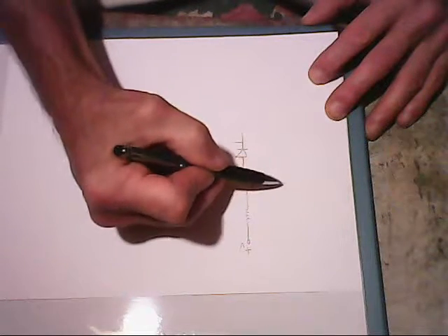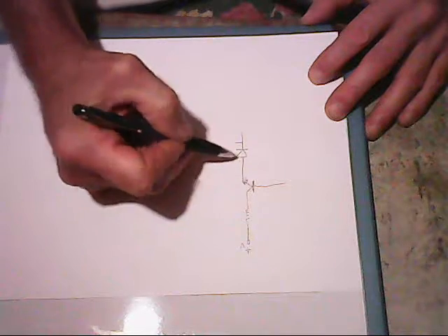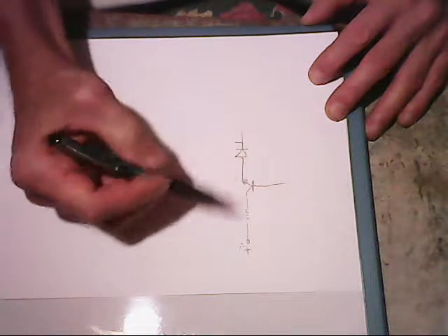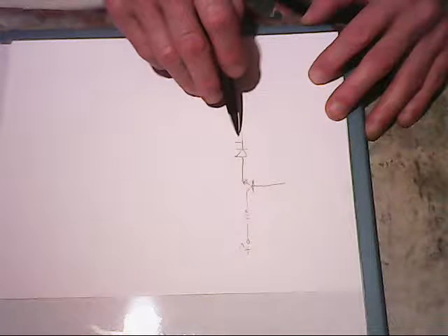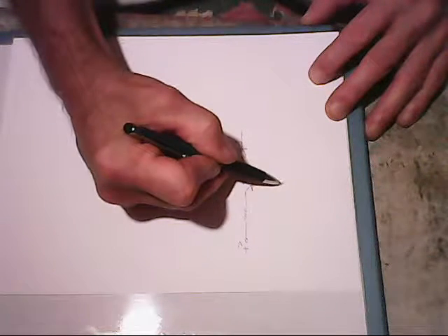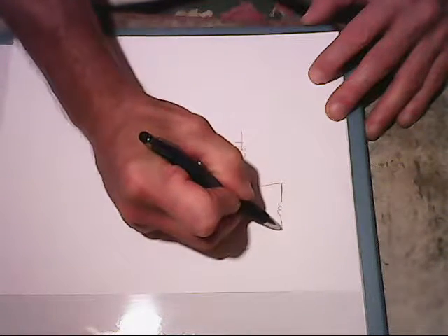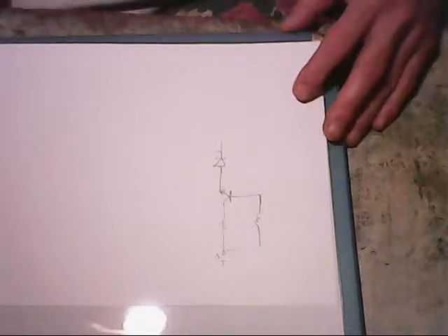So we want the transistor to be on continuously as a supply to the SCR, because we're going to have the load. The SCR is going to be sinking the load LED. So we need a transistor bias on here with a base resistor like that.